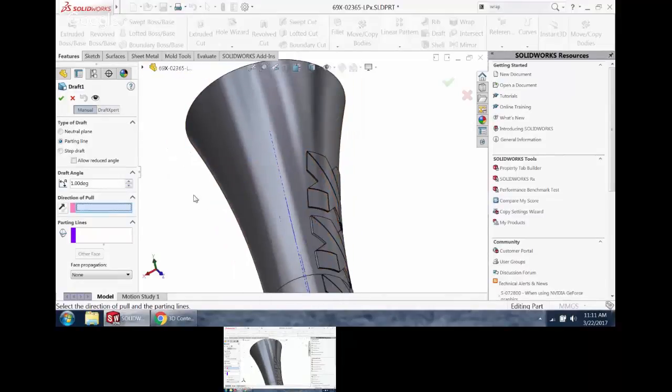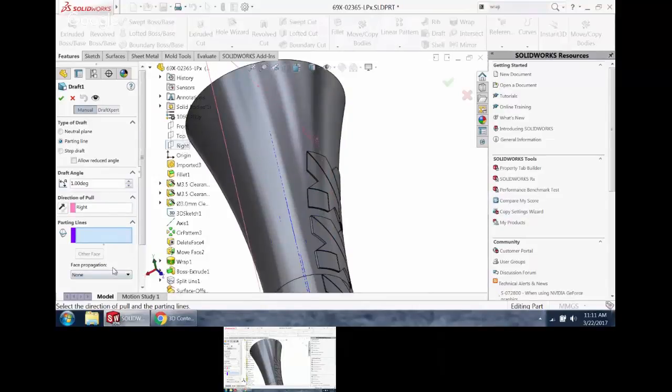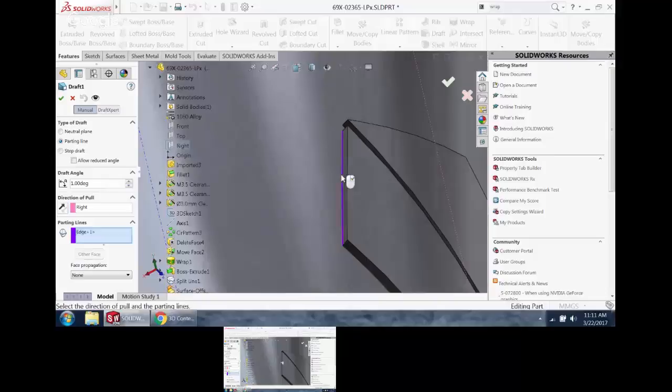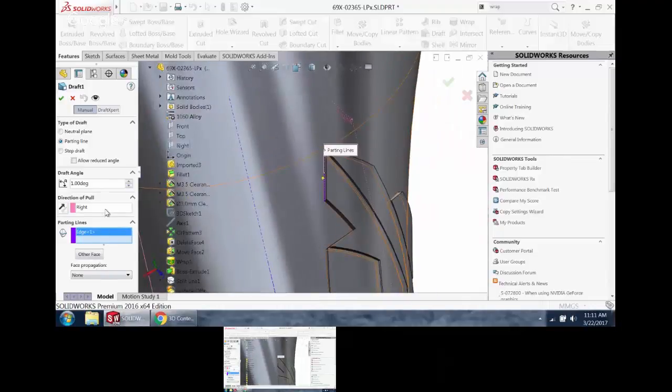You just need to use different edges. So it would be curve-driven draft from that, in the direction of the plane. Right, so this is my direction, but I would need to tell it where that draft is happening. So you can't pick a surface that would do all those things. Well, it will not let me pick when I pick direction of plane.